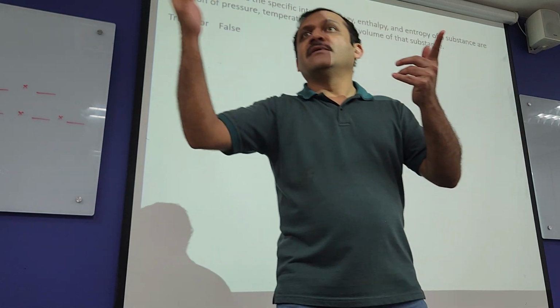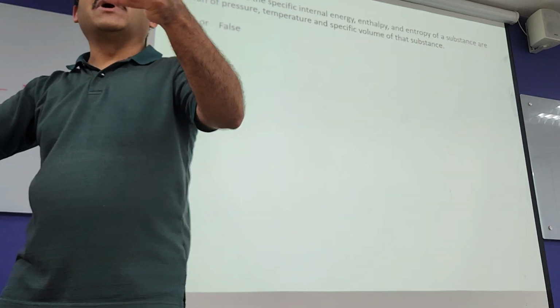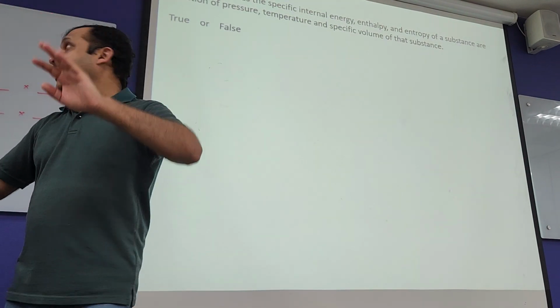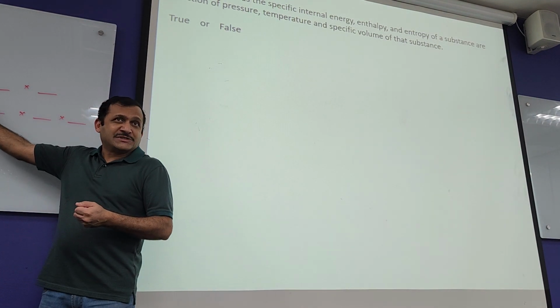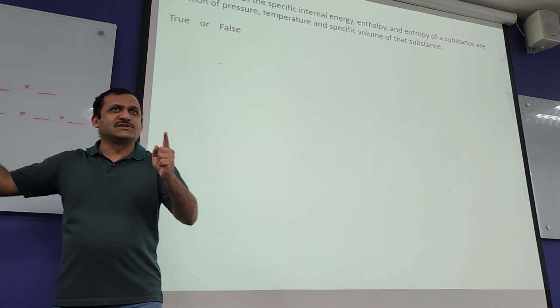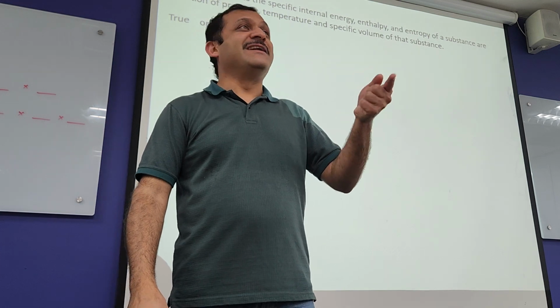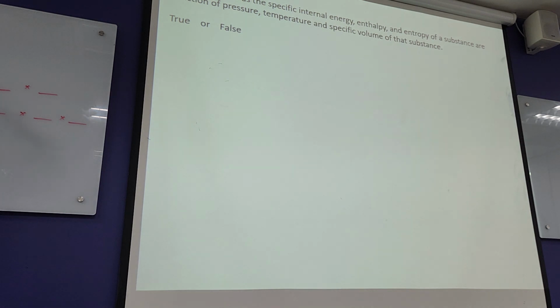Property. No, not pressure. Not volume, but something related to volume for internal energy. Yes. Now, mass will go in the bottom one, yes, for proportionality, there is a proportionality constant, CV, which is specific heat capacity at constant volume. I think you remember this equation. So, mass, CV and T.